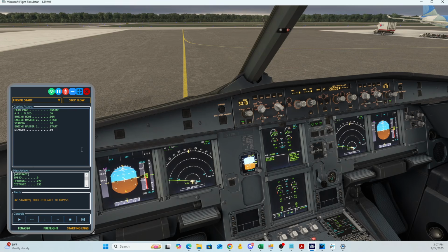So here's engine 1. We're just waiting now for the engines to both stabilize. And again, because we are using autoflow, what should happen, I think we put a 5-second delay before engine starts, and the after start flow will happen.